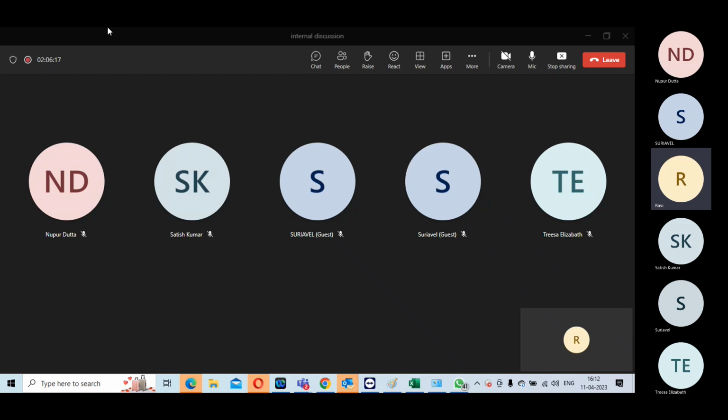It will place the CTS cells for that. Then it will do cloning of your clock gating to try and actually match your stuff. So if you are seeing that this particular clock gater is connected to 300 flops, one set is sitting there, another set is sitting over here. To balance that, to do buffering will be very difficult. So you clone that particular clock gating so that this module where it has to sit, you are actually keeping that clone like that. So you have to look at your distribution of your clock tree properly.